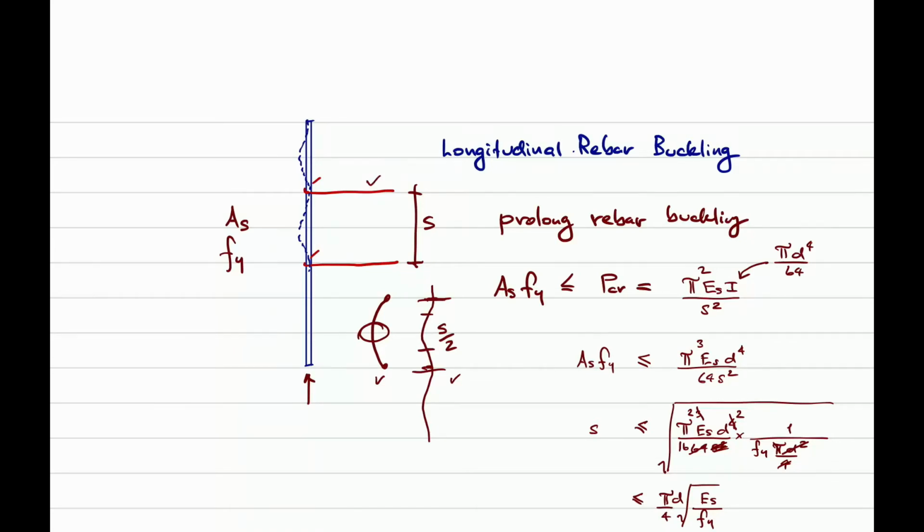So this part here helps limit the effective length of the rebar, but it can just prolong, because when you apply compressive stress to your RC member, your confined core has the pressure and it tends to push this outside anyway. So at the very last condition of the concrete failure, you will for sure see the rebar buckling no matter what.